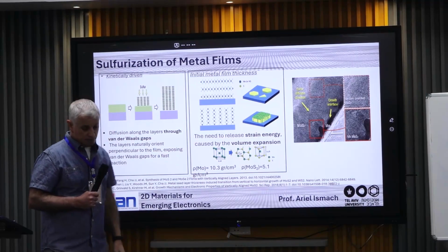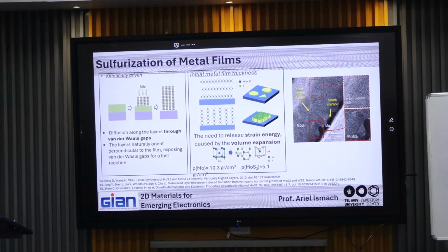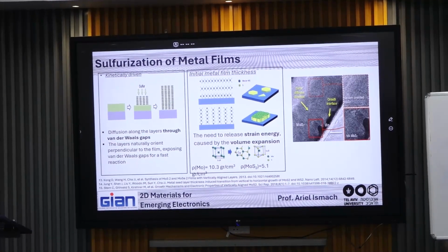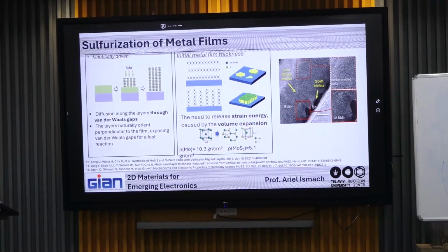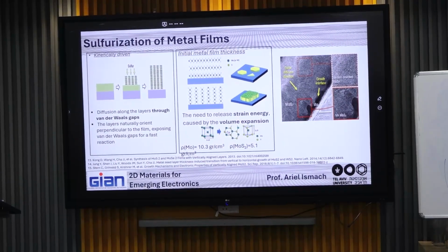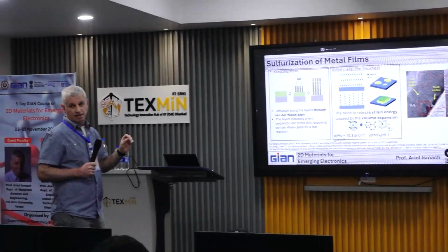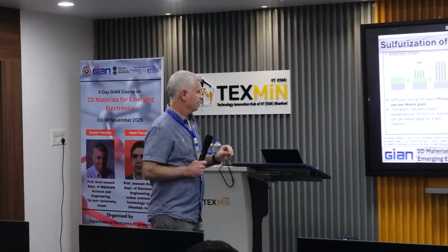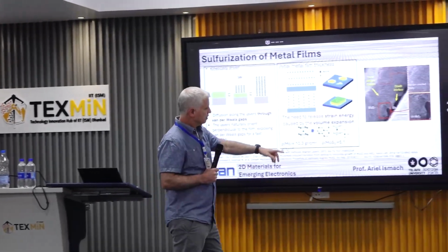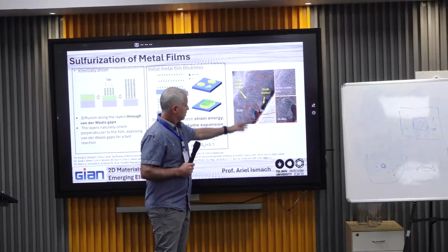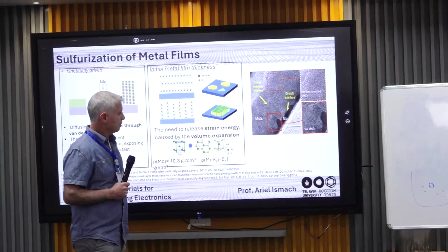And the problem with that is that depositing thin films with a thickness as small as a few nanometers is very hard. With PVD, these metals are very hard to deposit as thin films at such thicknesses. So usually by this method, you end up with 10 nanometers of continuous film. And therefore, you end up with the vertical growth, as you can see in these TEM pictures.